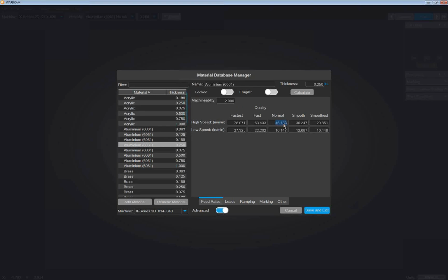So that's fairly typical. If you go from a 1030 nozzle combination with a 30 horsepower pump to a 50 horsepower pump with a 1440, you'll see about a 40% or so increase in the speeds. Now, if you decide that you're going to run your pump at a lower pressure, or you're going to run more or less abrasive, let's just remember this number right now, 46.13.